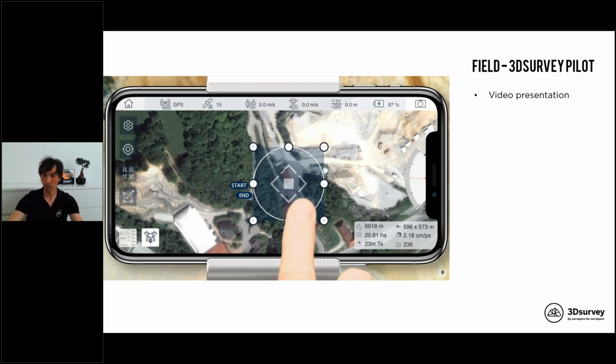And what I would like to repeat here again is sometimes it's really hard to center the circle over the accident area, and in this case maybe the camera will not point at the center of your model, but nevertheless you can leave the drone flying in circle mode and correct the position of the camera. You have a gimbal setting with the roller, you can put the gimbal up or down to really focus on your area of interest in the accident site.